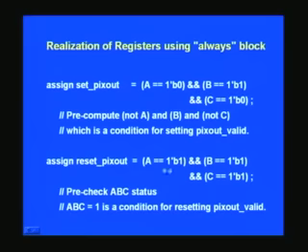And notice that in logical statement we need to put double AND as such, right. And of course in assign statement, even if you put just one AND, it still accepts, but as a normal practice you should use this, because in sequential circuits we can put the logic inside the always block. There if you do not follow this and just put one, the tool will complain.